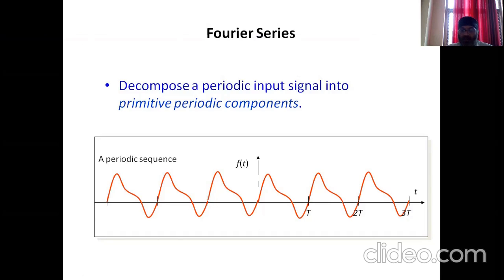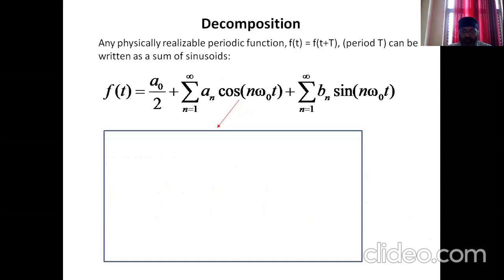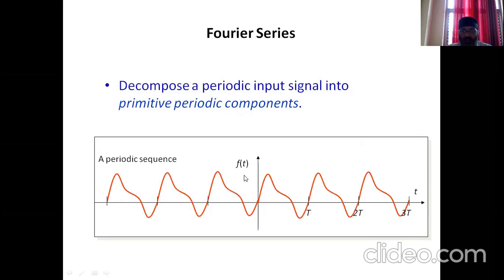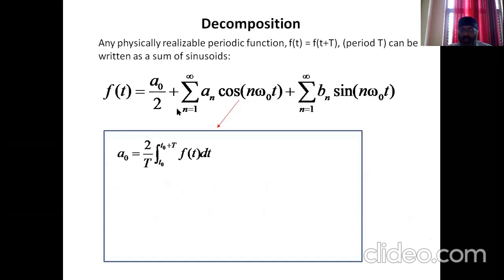And we want to get rid of them so that we get a clean sinusoid. That's the whole idea behind using Fourier series to do harmonic analysis. And once harmonic analysis is done, we can use filters to remove all the unwanted harmonics, to remove the distortion.